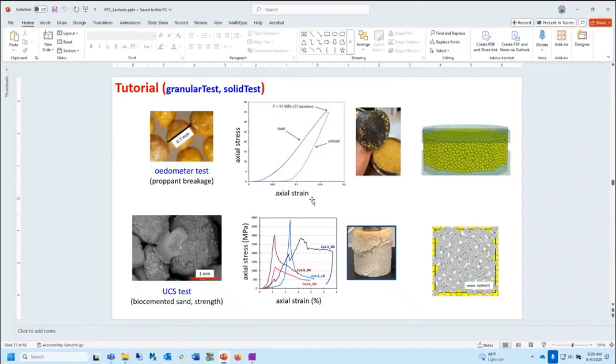So we apply on the strain control test. So yes, we tell it the rate that we want to deform or apply the displacement. Okay, so you tell the machine, I want to apply 0.1% strain, and you also tell it how fast to move that thing. So right, the machine itself doesn't operate on strain or stress, it's force and displacement. So we apply displacement over seconds.